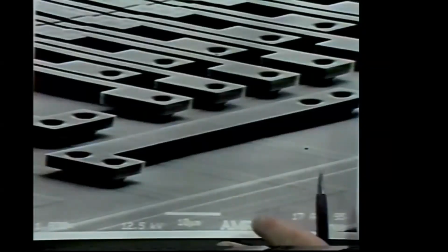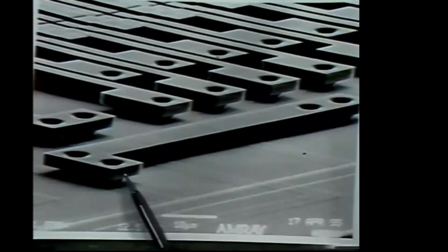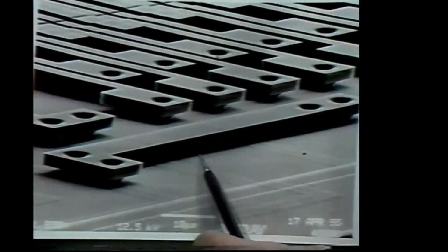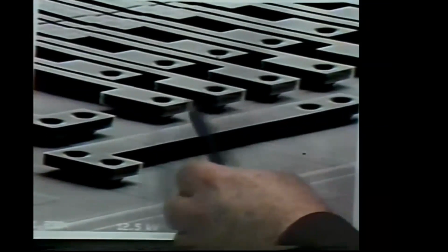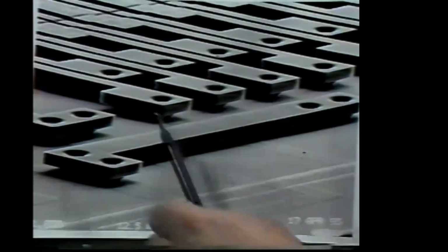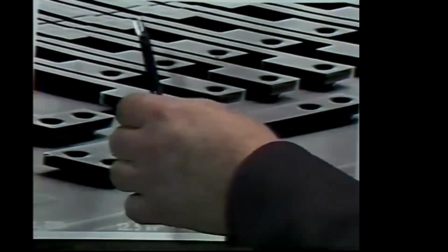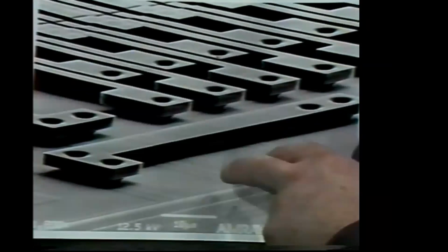Just a brief look at the actual material. You can see in this SEM photograph that the polysilicon material, 2 microns in thickness, is indeed suspended above the substrate. Looking under one of these anchors, these are the anchors to the substrate. And there are very small stress gradients within the material, which you can see by looking at the ends of the fingers relative to the things that are fixed above the substrate.